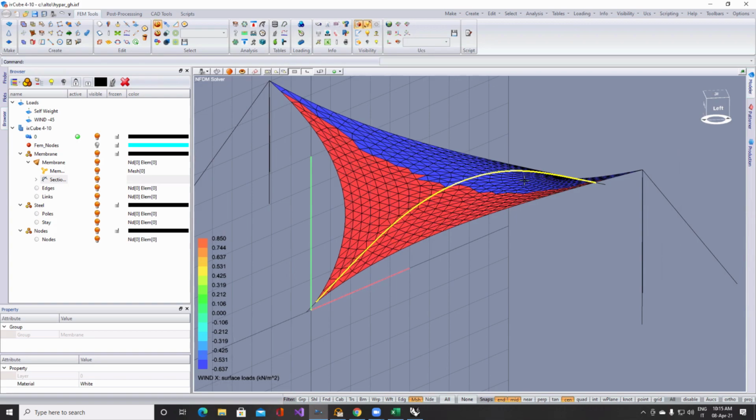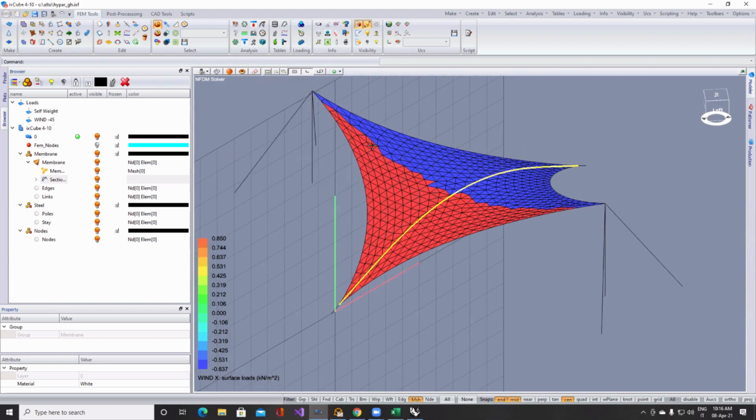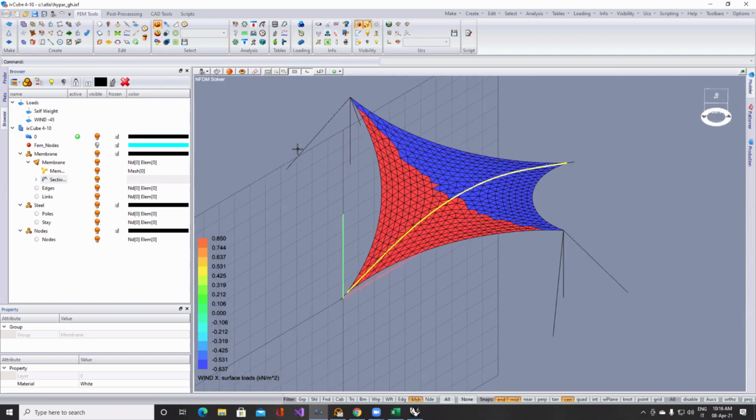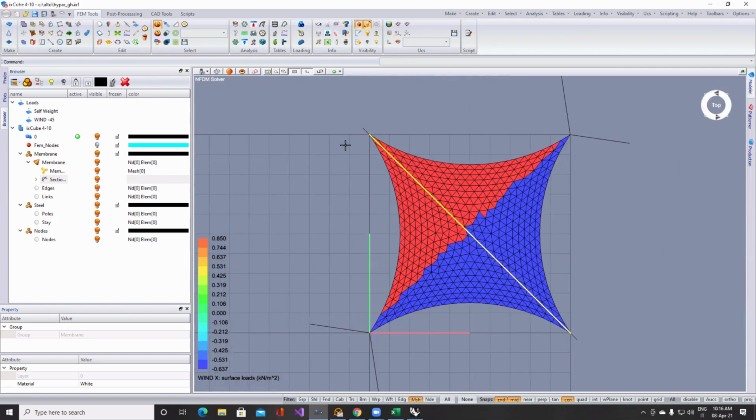Based on the cross section, we go into the Eurocodes or into the codes that we are using, and we evaluate the pressure, the CP values, based on the geometry. Clearly, if the geometry is complex, maybe we have to make more than one slice. Based on these slices, we are able to evaluate the behavior of the wind in this direction. Looking from top, the wind is blowing in this direction. And which is the behavior based on this curve? It will have an initial pressure in the beginning, and then it will become suction on the other side.